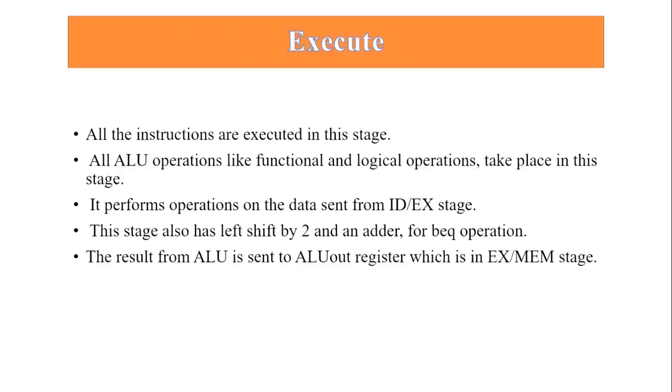In the 5 stages of MIPS processing, all the instructions which are received from the instruction fetch and instruction decode stages are executed in this stage only. All operations like functional, logical, binary operations take place in this stage. This stage also has a left shift and an adder. The result from ALU is sent to ALU output register, which is in memory stage.